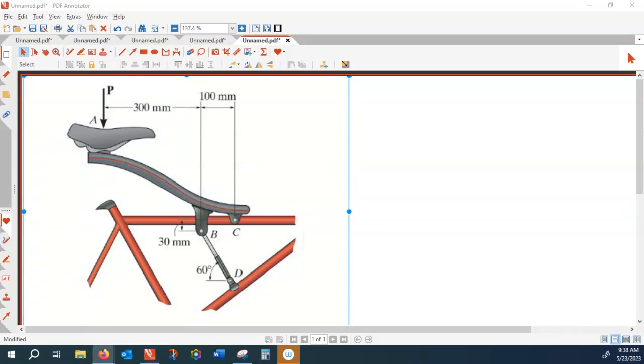So what happens if I release that one external force? The reactions should be exposed at B and C. So two forces here, two forces here, four forces. But given that you know this one is a bar, a two-force member, it can only take a force along this axis.